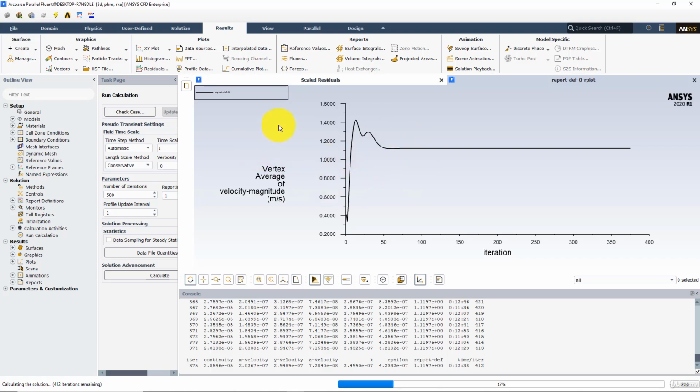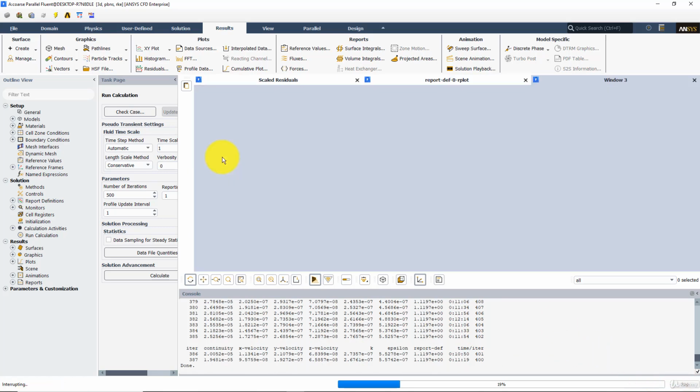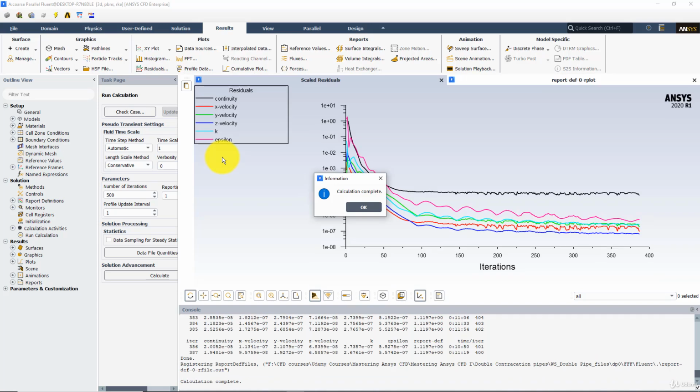So if we start with the first mesh where we had very much transient flow, and the change between the two intervals was huge, and then in the second case where the change was less than 1%, and now here is almost a straight line. So this is the effect of proper mesh resolution and creating the proper mesh for the case we are solving here.